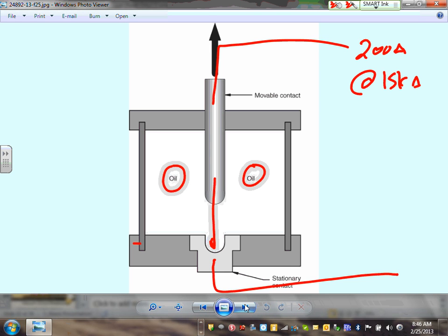There's so many designs of it. There's so many gauges when you go into the medium voltage. There's a lot of gauges, the pressure, temperature relief, and pressure relief for all these, because you don't want it to explode. You have oil. So the idea is it will minimize the arc, and immediately when it arcs, it's like you have water, or liquid, right at the top of the arc. Any comments, any questions? That's your oil. You have an oil inside it. Does this have an oil? No. We rarely use this, if any, in medium voltage. I'm not aware of anything in the low voltage system that we use.